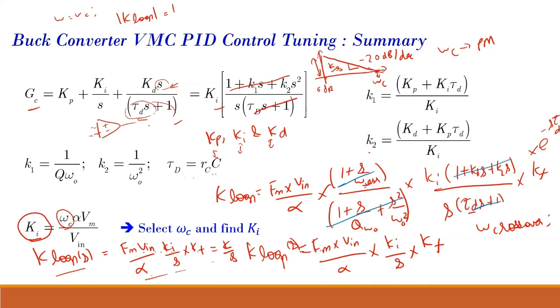That low pass filter is physically realizable by connecting some RC network across the op-amp, or inside the op-amp itself, after a certain bandwidth of the op-amp, it starts attenuating those frequencies, so that it effectively brings about this tau d s plus 1.